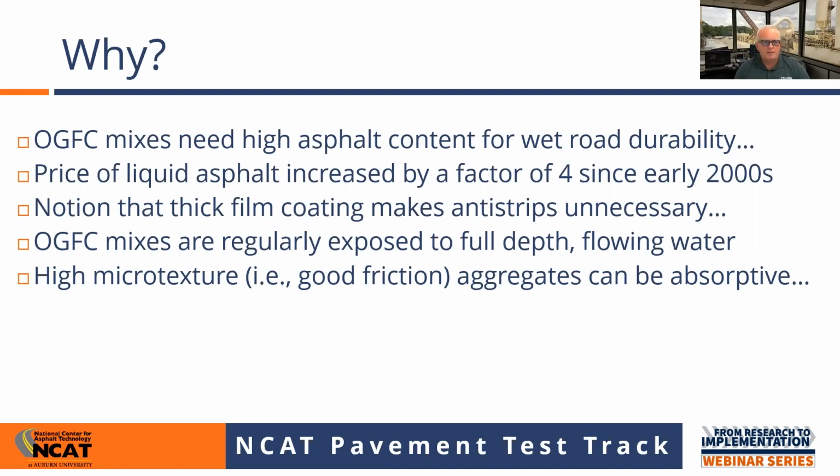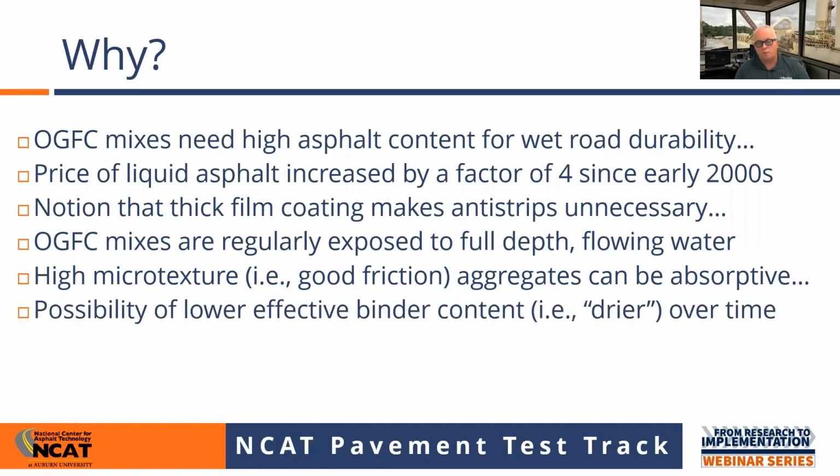So we like to use high microtexture aggregates because they provide us with good friction. Some of those aggregates can be absorptive. And if they are absorptive, then we have the possibility of having a lower effective binder content over long periods of time. So the mixes can possibly dry out on the mat after placement.